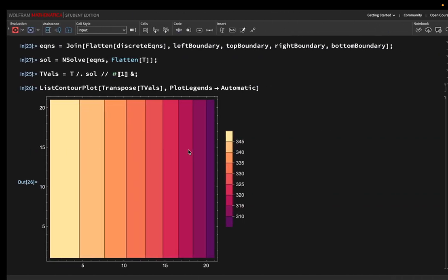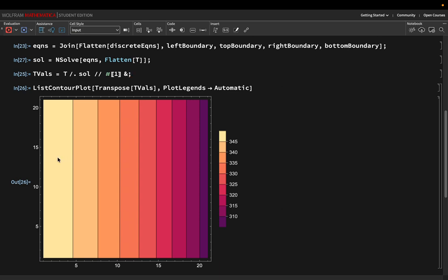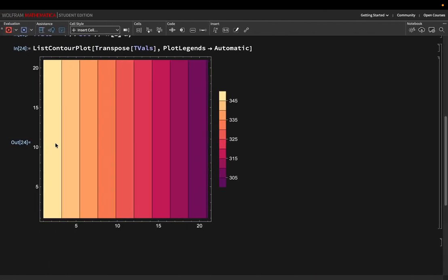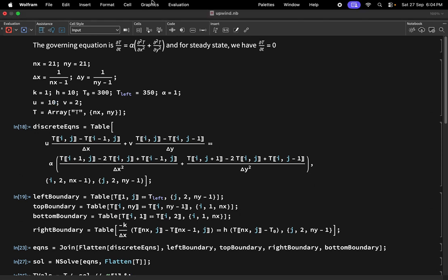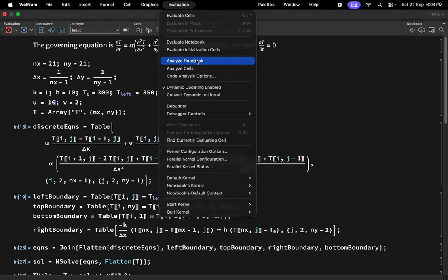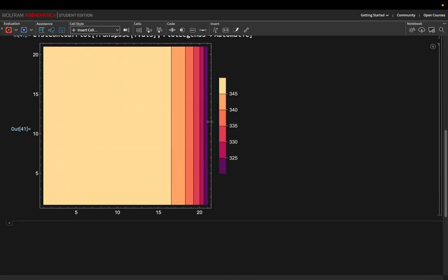You can see the difference between these two. The width of this particular one is a little higher than the one you can see here. This is essentially because we have a velocity here, so advection is carrying the temperature a little forward. For example, if I increase this to 10, then you can see the difference clearly. You can see how much it has propagated. As the advection velocity increases, this would get propagated more and more downstream.